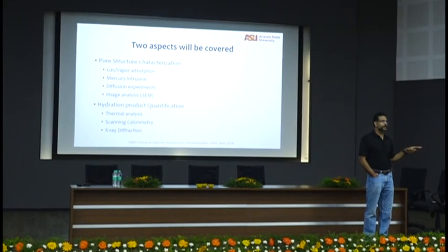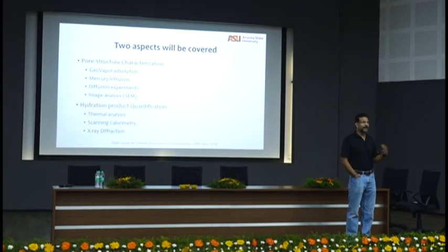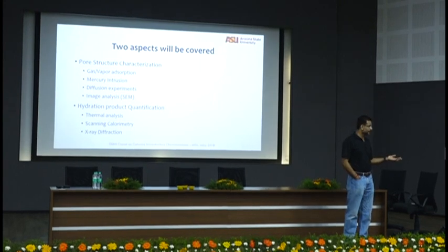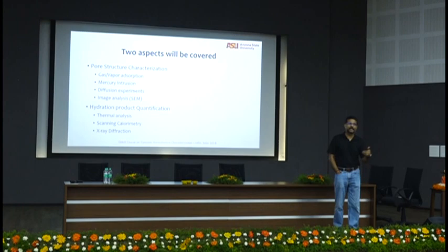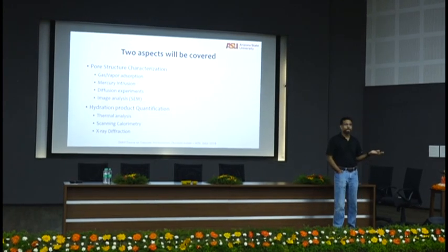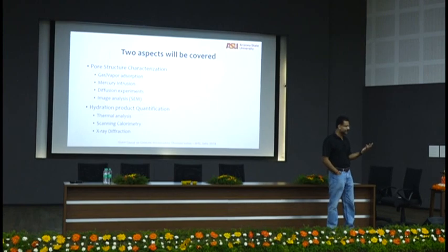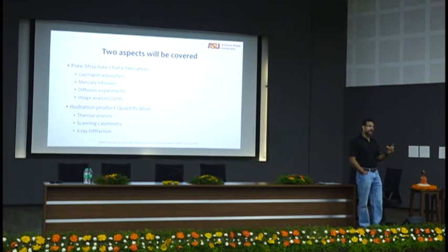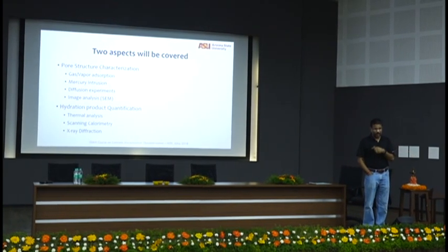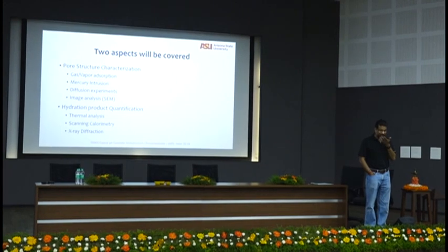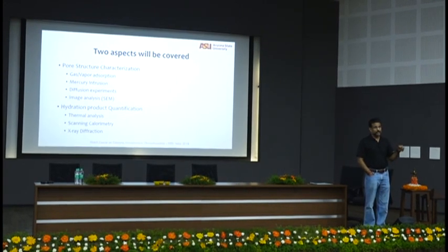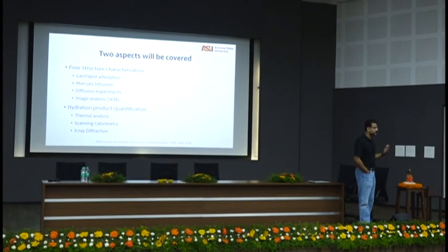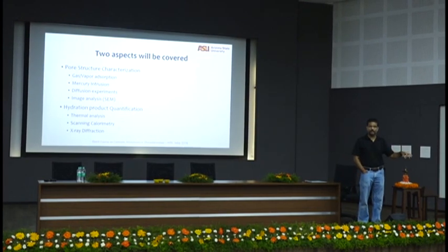Right? All the durability problems are caused by pore spaces. Like I said, you may have a certain porosity that's no guarantee of good durability or bad durability. It depends on how tortuous, how connected the pore sizes are. Especially when you have chlorides, and there are a lot of complicated things associated with it. Sometimes both hydration product quantification and pore structure quantification in combination will have to be done. Classic example being corrosion. You need the pore structure because chlorides are going through the pore structure. So you have to quantify the pore structure to find out how the chlorides are going to get to the reinforcing steel.